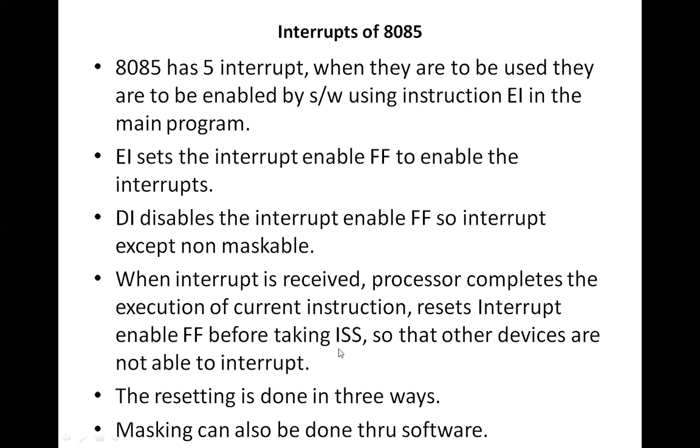And what is in the interrupt service subroutine? It will contain certain instructions which will be helpful in transferring the data. So before it executes the interrupt service subroutine, it will first reset the interrupt enable flip-flop so that other devices cannot interrupt the processor.